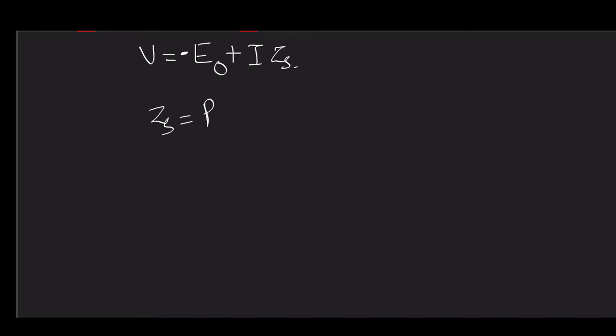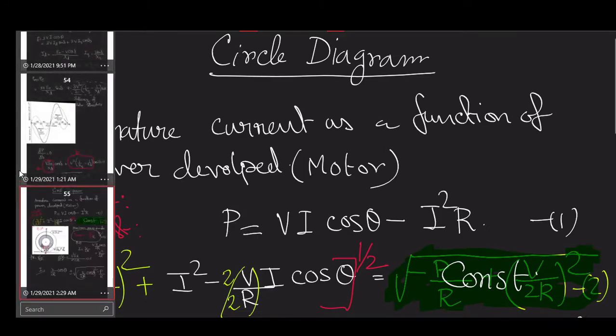Now Zs is equal to what? Zs is equal to R plus jXs, the synchronous impedance, and they have considered it as counter EMF. For counter EMF consideration, everything will remain the same. Only their argument, and that is not a bad argument, is about what we draw in the case of a motor. Okay, the motor phasor diagram, I think I have it.